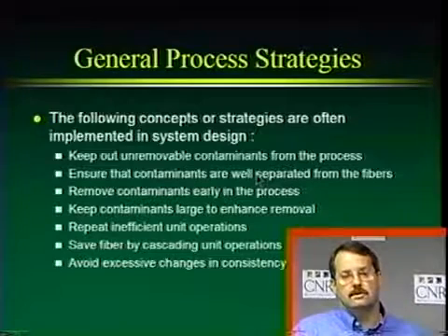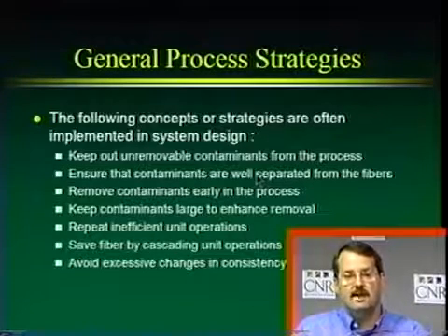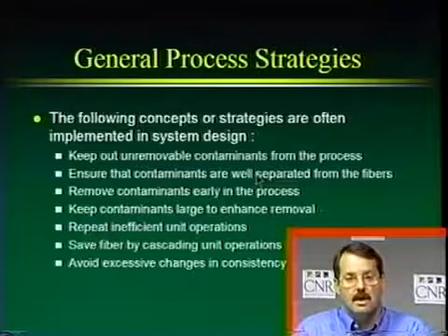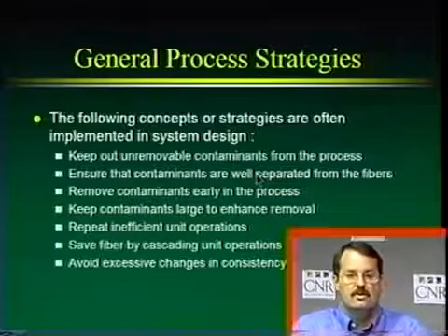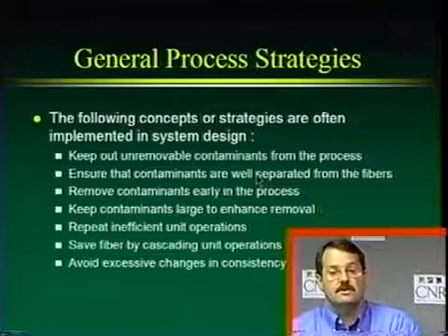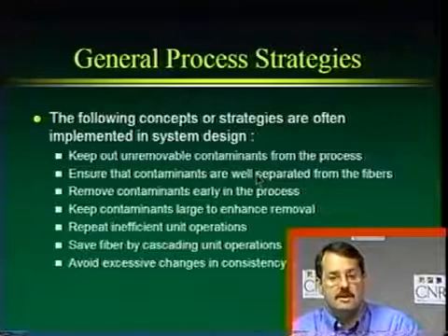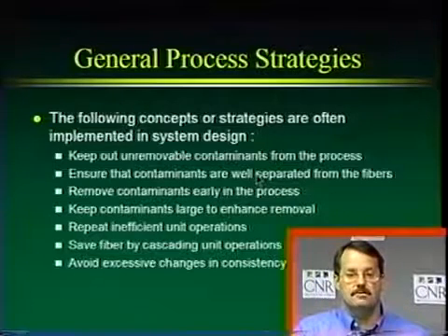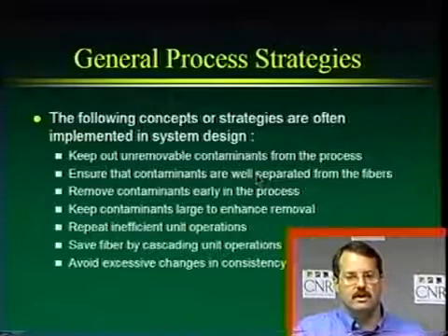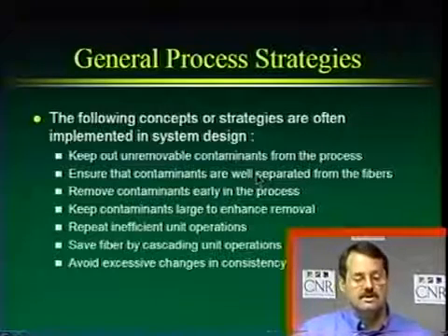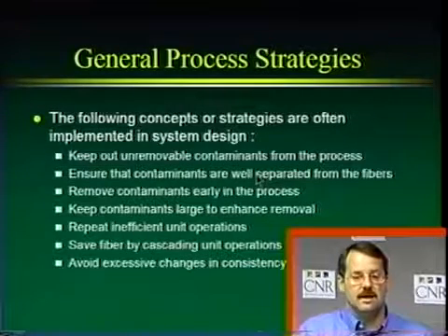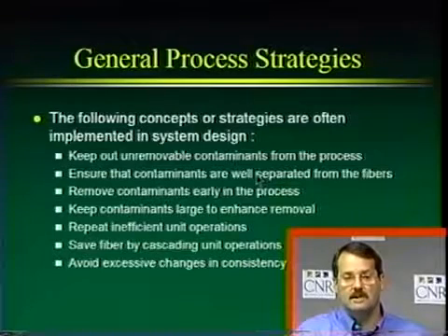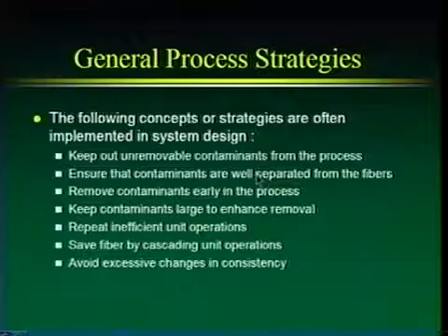Another general rule is instead of breaking contaminants, we'd like to keep them large, at least early in the process, so that we can enhance their removal. They're easier to remove if they're bigger. For some inefficient steps that are important to us, like flotation deinking, we will have to repeat those steps. I put inefficient there, but sometimes they're not inefficient. It's just the limitation of the technology. So we'll have to repeat some unit operations to get the cleanliness that we need.